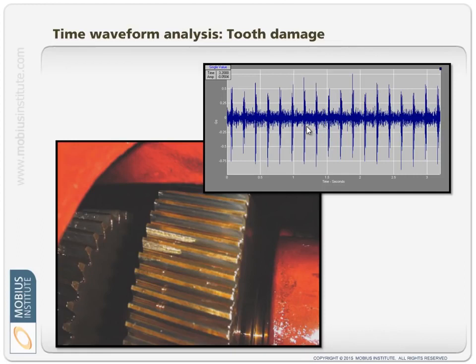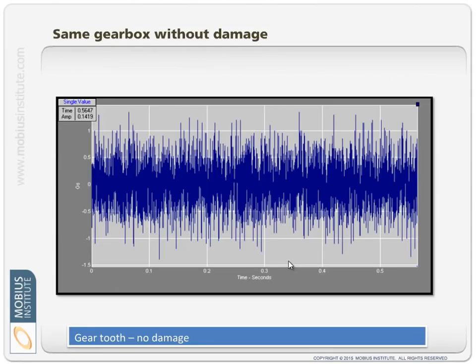And there are some cool ways that you can look at time waveforms. I think it's pretty cool what we're seeing here, but you can mark it off in revolutions of the shaft. You can look at it wrapped around a circle and see that once per revolution it's occurring. All really cool techniques, but it's telling me exactly what's going on. By the way, we should do oil analysis as well, because the pieces of metal would go into the oil and we could detect that. So, a very useful technique in parallel with vibration analysis with gearboxes.